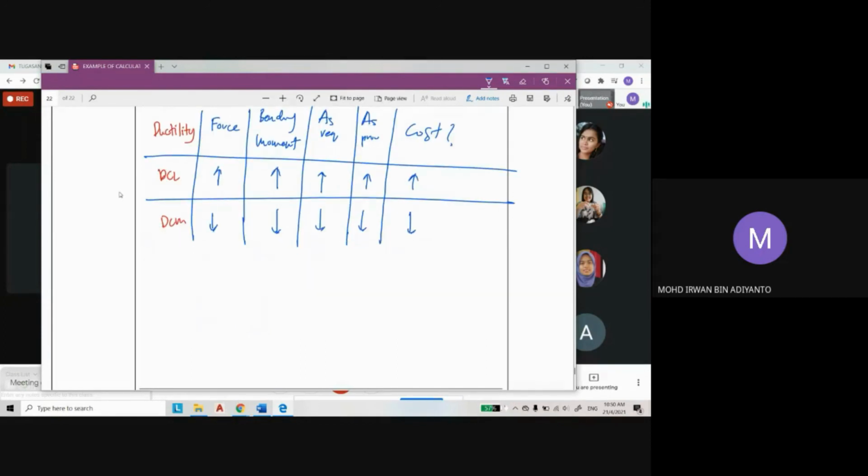Because our design strength is this one. Okay, let's say this is our design spectra for SDT1, and this is the type T1. Okay, this is the spectra, and this is for DCM because the Q factor is 3.9. This is for DCL. Q factor is 1.5.